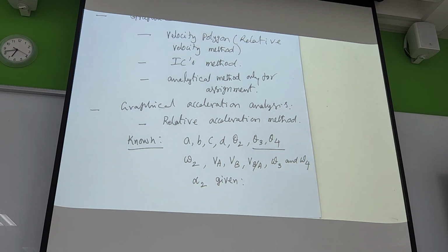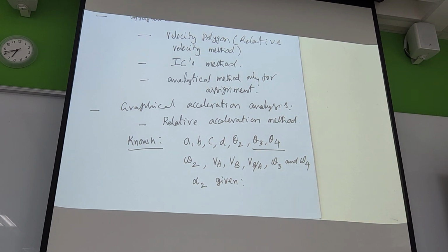Now after this what? So once you complete your position analysis, velocity analysis, acceleration analysis, the next part is the force analysis. Okay. So next we look into the force analysis. So by the time we start the force analysis, that means you know all these things. You can plot the mechanism to scale, you know the velocities of points, you know angular velocities of the links, and also you know the accelerations.